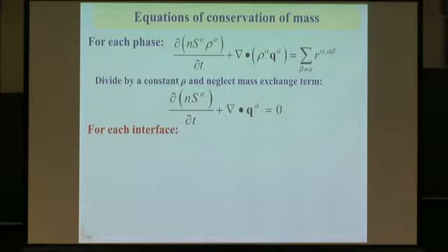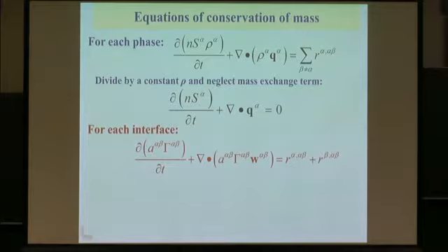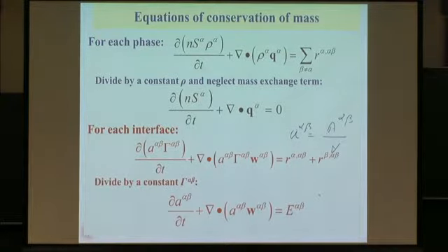But what we also get extra through averaging is that there is a similar equation for the masses that are potentially accumulated at the interfaces. And then it looks like this, where gamma is the mass per unit area of interface, and this A is called the specific interfacial area. This is the area of the alpha-beta interface per unit volume of the porous medium, the REV. So it's called the specific interfacial area, and then there is a balance for this. If the mass per area is constant, then we get an area balance equation. So we have an extra equation.